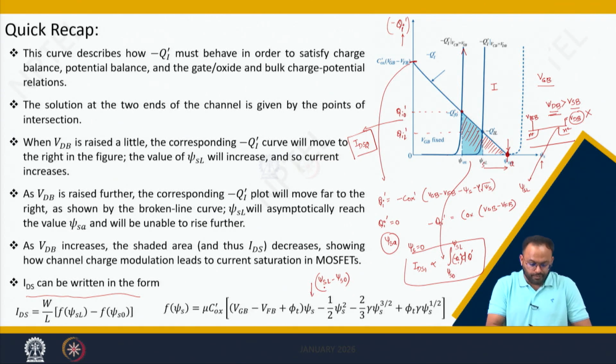We also derived how to calculate the surface potential, charge and the current as a function of x, in the sense when you move from source to drain. So along this dimension, how you find the inversion charge as a function of x, the surface potential as a function of x, and finally how you calculate the current as a function of x.